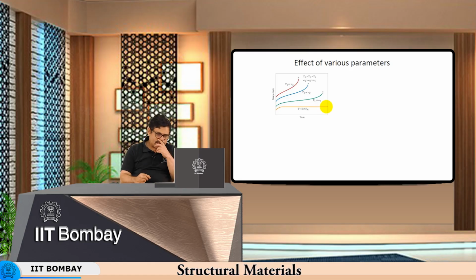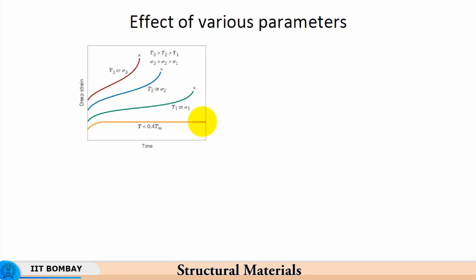What is the reason for this? There are many possibilities or many issues here. Once the temperature comes into play, the grain boundaries are the ones which get affected the most, because temperature increases the mobility of atoms, and since the grain boundary is the region of the maximum disorder, the maximum effect of temperature falls on the grain boundary, and therefore, the diffusion of atoms is much faster at the grain boundaries. So, gradually the grain boundaries tend to become weaker.